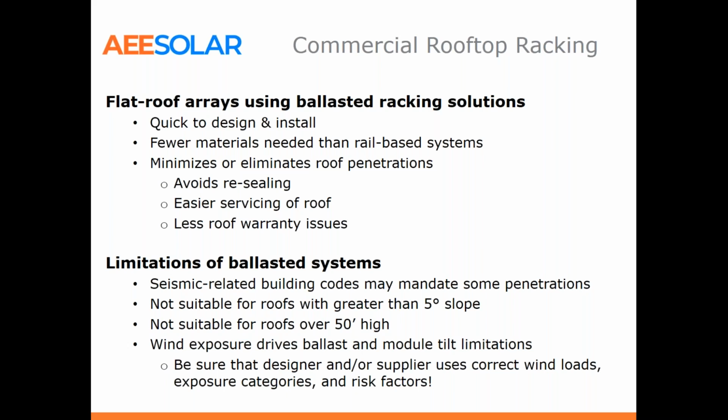Well, that's because we're designing to the right wind speed and exposure, and we want the panels to stay on the roof. I've taken a couple of calls in the past couple of years where a competitive design system had a failure because it wasn't held down enough by ballast or penetrations, and when you dig into it, either the wrong wind speed or the wrong exposure category was used.